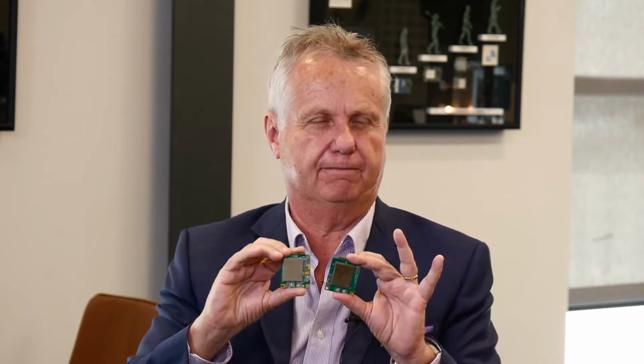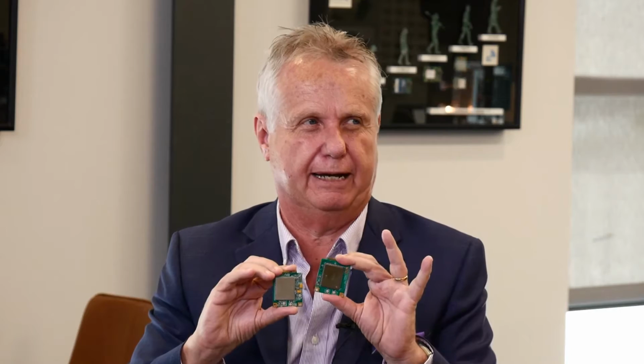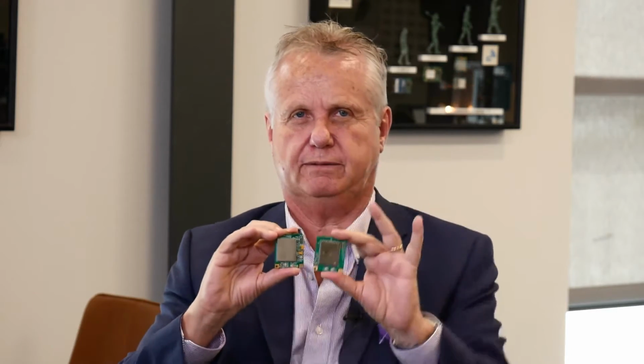So just to be 100% right, here I've got a cellular V2X transmitter, and here I've got a DSRC transmitter, and these are the real things. So what you do is, under software control, you transmit the one, and then you transmit the other. You don't actually broadcast them at the same time. So you transmit like this, every 10th of a second.